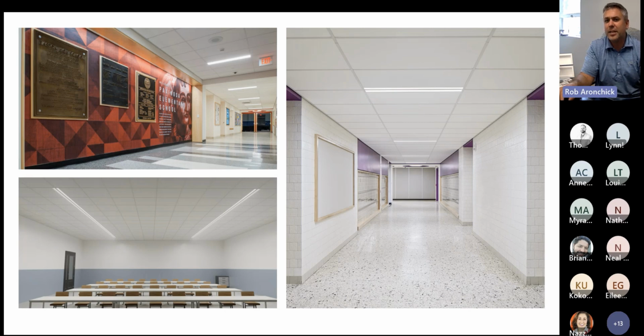We do a lot of education, as I mentioned. Spacing. So with our optics, we utilize an edge-lit optical system, and we're really distributing the light with a nice asymmetric batwing distribution so that you can cut down on fixtures. In our case studies, we show how you can sometimes get rid of a whole row of fixtures when you compare it to a 2x2 or a 2x4. In this corridor, 14-foot spacing by utilizing the Duo fixture.